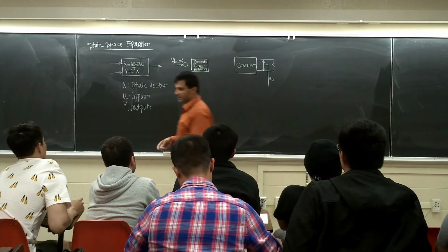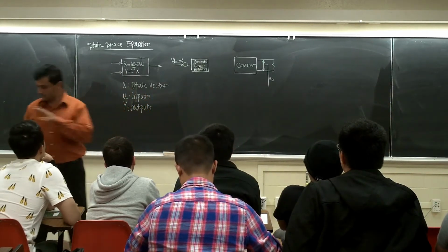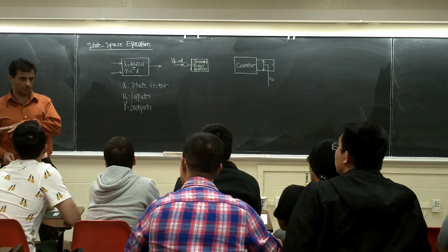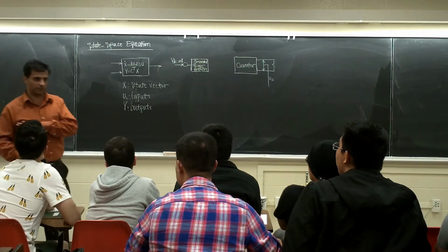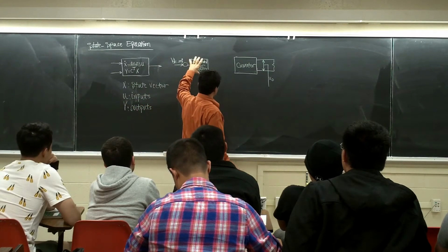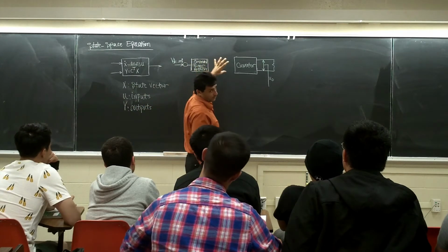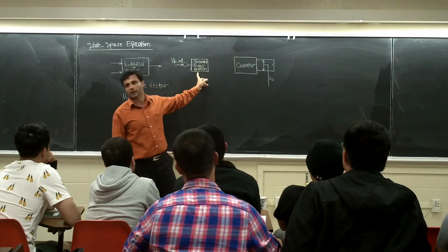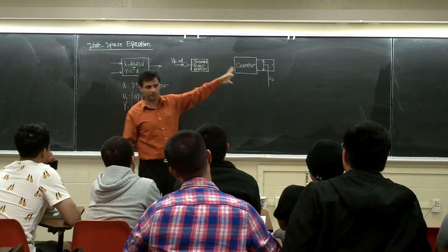But they are expensive. They are difficult to design. Digital controllers are much more flexible. And most people now use the digital controller. Now, we call this one the compensated error amplifier. On the flyback converter you guys are working with, it's called just PI.